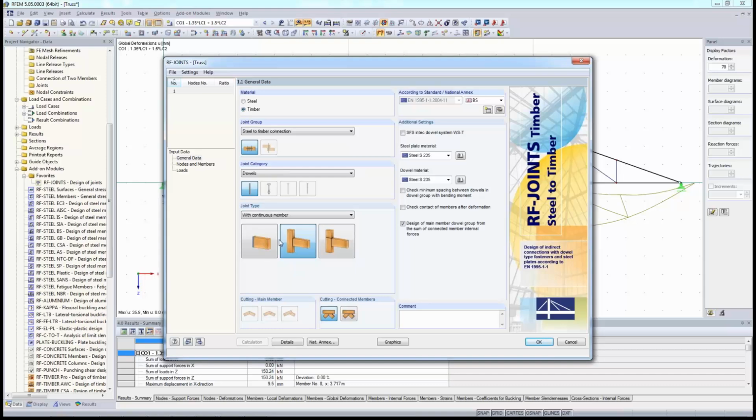For this category, we have now 3 types of joints. The first type will be main member only. It's not just for one member. You can have up to 50 or more members on this joint type. So that's all possible. And it's pretty smart to do it if you have a very sophisticated structure, or if you have just little pieces of inner beams beside, or if you have a cantilever attached to a concrete wall. That's actually where you would choose this connection type.